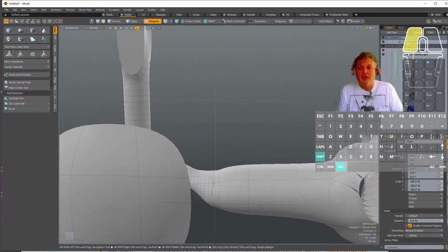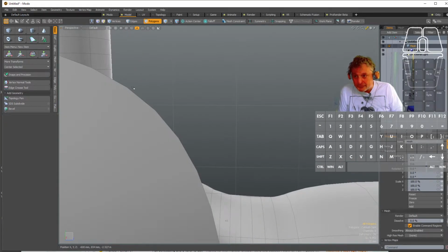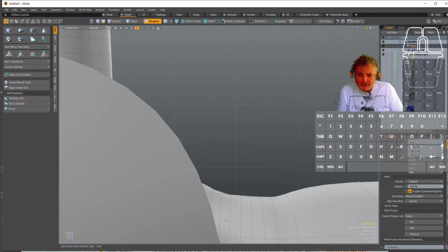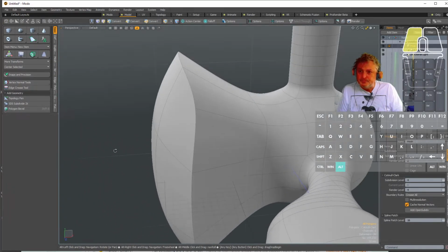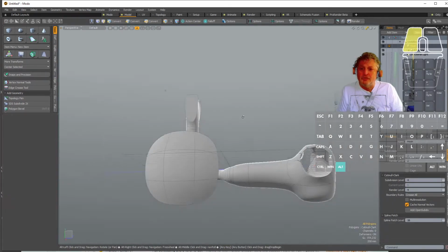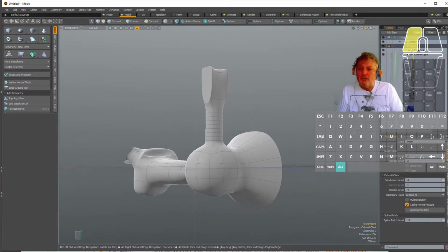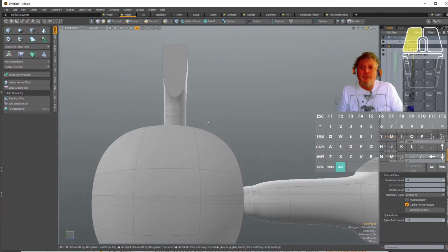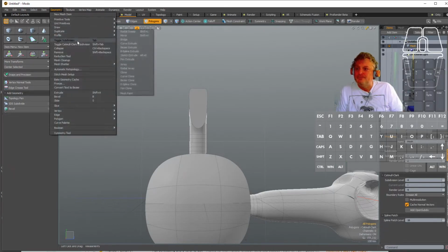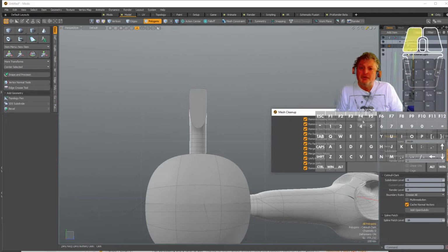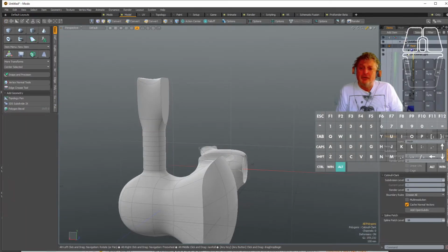Another thing worth seeing, even this you'll see is made of straight lines. See that along the edge there? I can adjust that in the object if I go under Surface. We want to increase the subdivision level. I'm going to go to 4 and 4, and you'll see that's a much smoother edge now. It's still made of straight lines. It's just straight lines that there's more of them there, so they look like a curved line. I'm also going to run another mesh cleanup because I've done a lot of stuff to it. Mesh cleanup. Well, no elements to clean, which means it's okay.